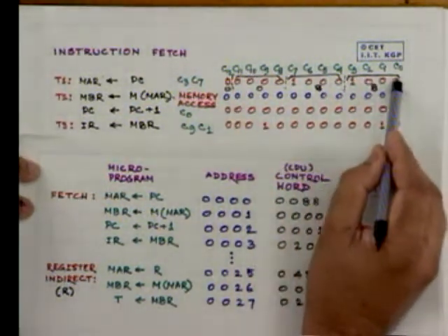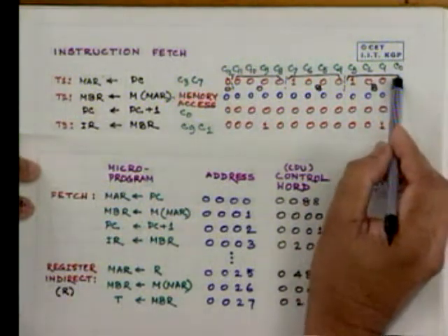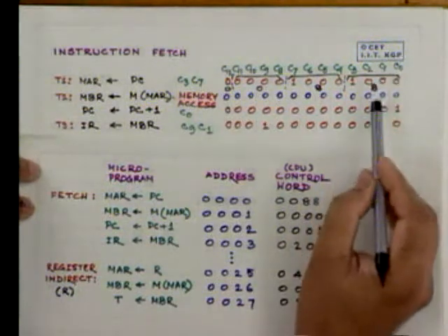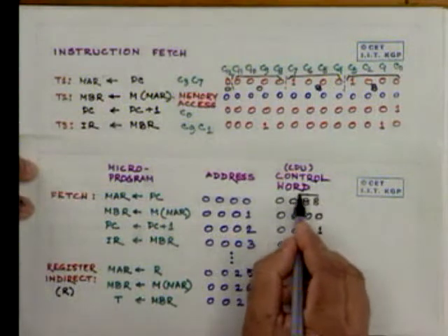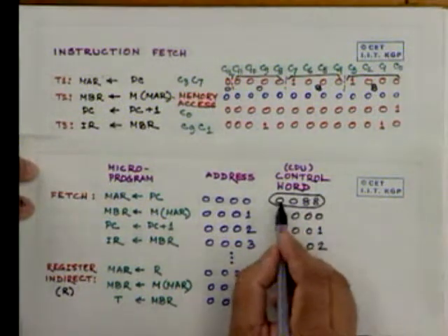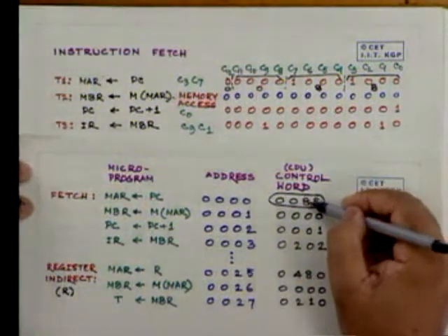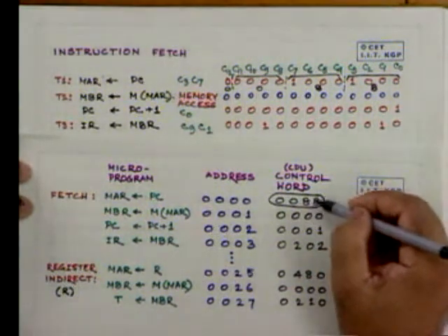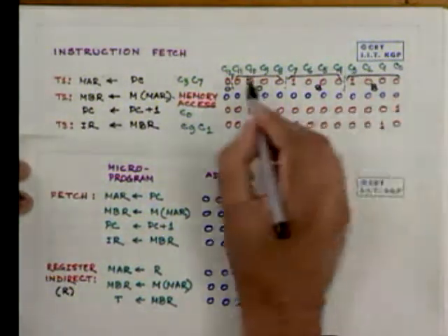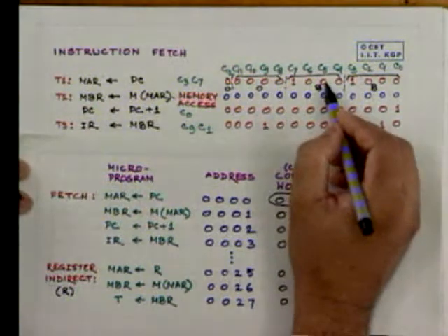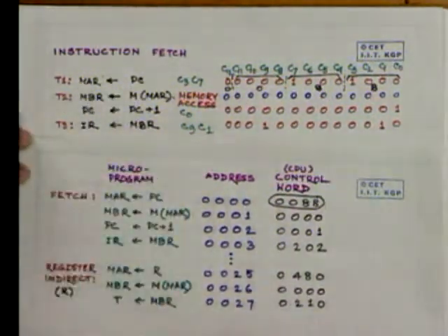And this, if we now send to the different control signals, for example, these two control gates, this to C0, this to C1, then as we read the content of this memory location, the output of the memory location can be sent directly to the different control gates, which will effect the control that is desired, program counter going to memory address register.